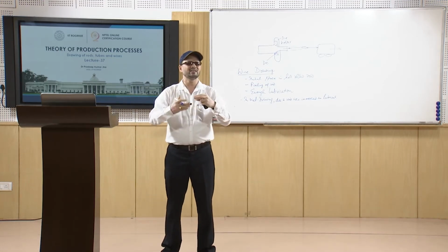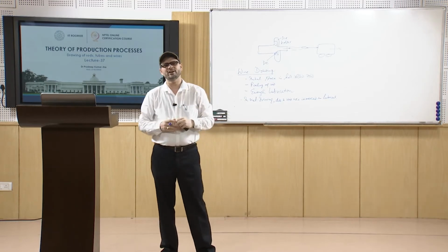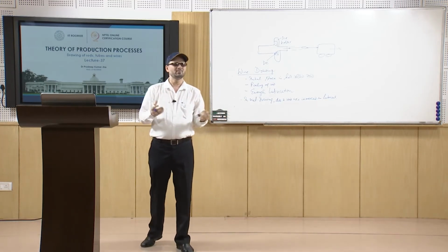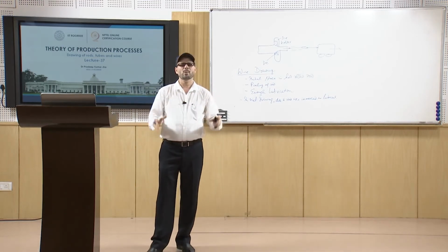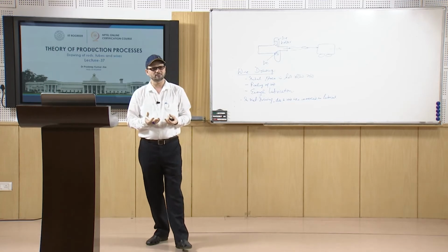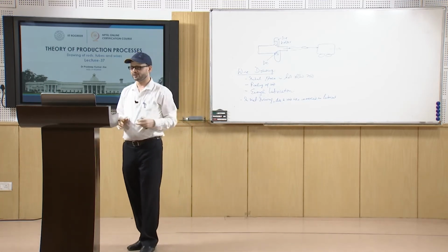You can see that by changing the cooling rate, certainly that is a metallurgical principle, you can control the type of grain structure, fine pearlite to coarse pearlite or so, depending upon the cooling rate conditions.